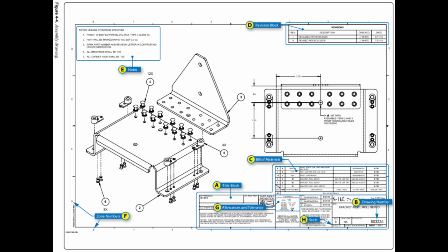If the plus and minus allowances are the same, you will find them presented as 0.225 plus or minus 0.0025. The tolerance would then be 0.0050.